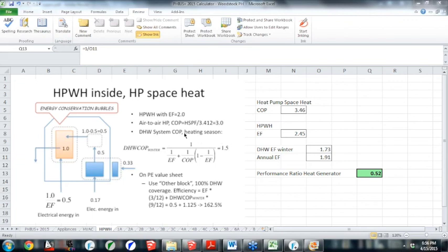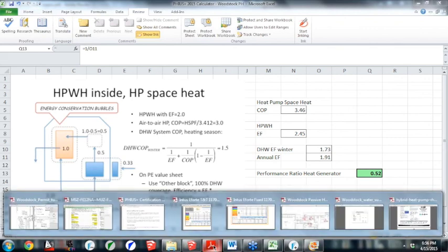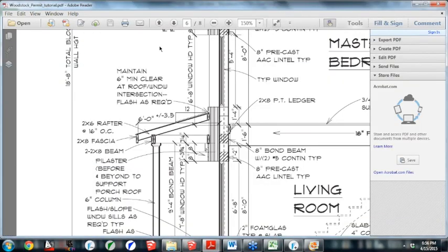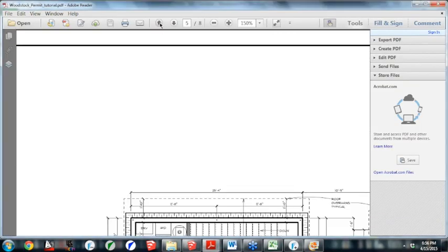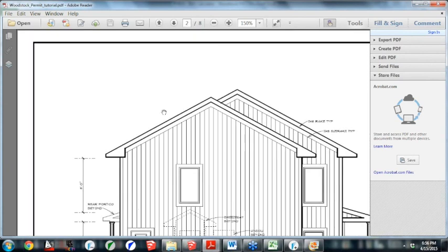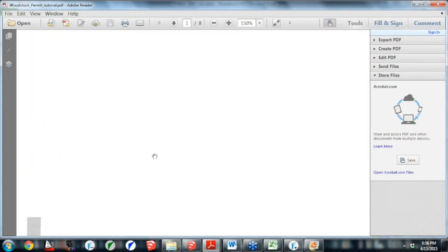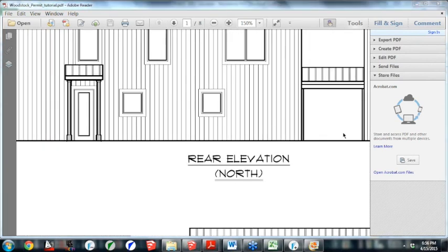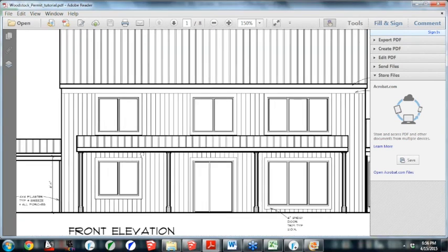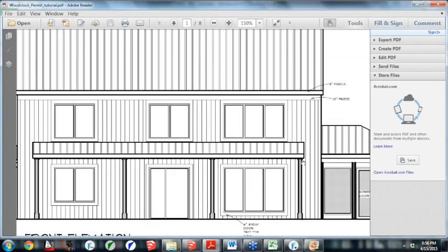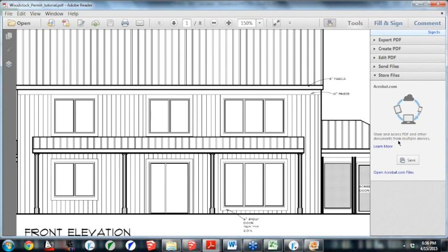This is a good question, this next one. So covered porches in the SketchUp model. Does WUFI recognize these as shading devices? So there's this porch on the front of this project. If I would have added this into the SketchUp model and into WUFI Passive, would WUFI Passive know? And the short answer is on the static side, not yet. It will soon, but right now you still have to input it as an overhang.